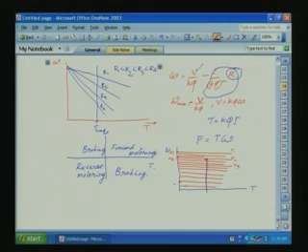I have to come here means already motor is running at this speed, depending on the torque curve here. Now, to reduce it, already there is kinetic energy in the system. We have to take back the energy from the system as fast as possible, so that the system can decelerate. Take back the energy means we have to reduce the current to 0, and then back EMF should drive the current back to the source. So, the power is reversed, such that the machine will slowly decelerate.